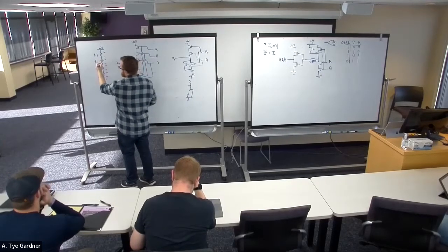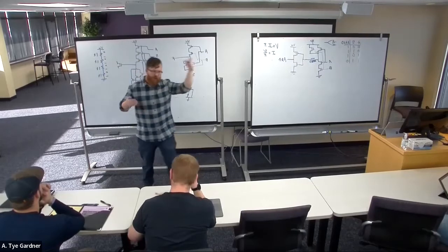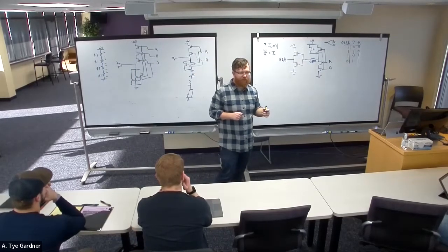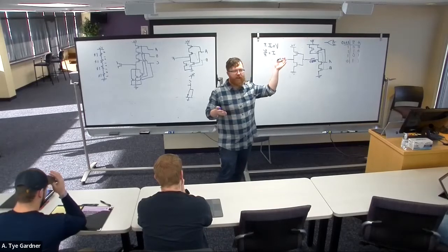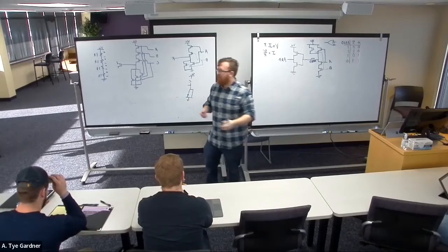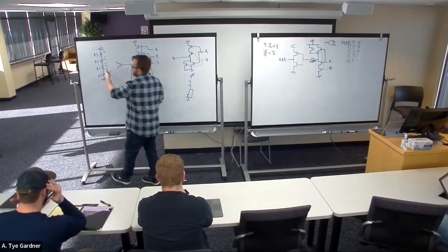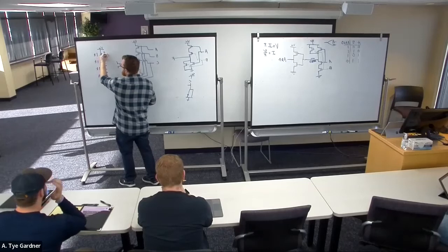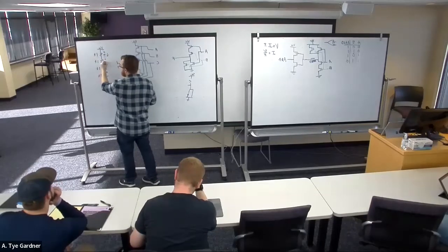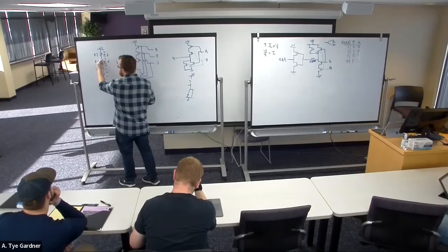Each of these voltage drops is going to be just 1/4 of the 5 volts, because they're the same device, and I told you they're linear. So if they're the same size, I don't care what the order is. And so what that kind of intuitively ends up implying is that this is 1/4 times 5 volts, and this is 1/4 times 5 volts, and 1/4 times 5 volts.